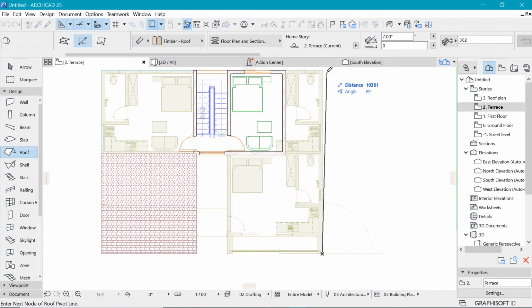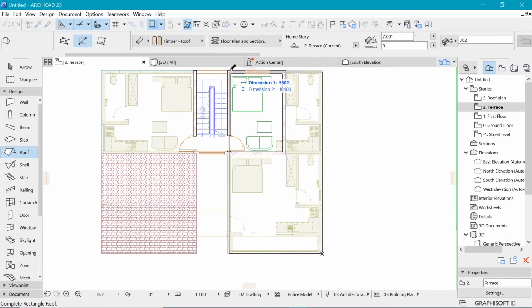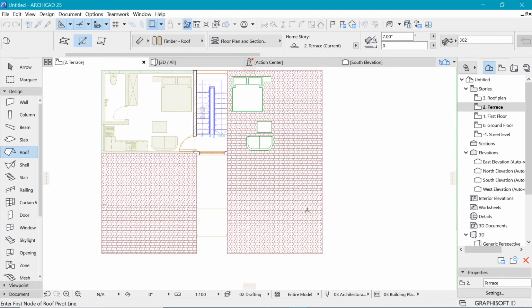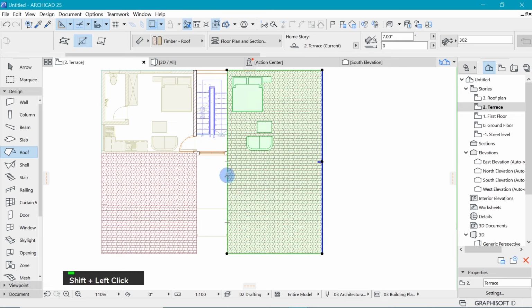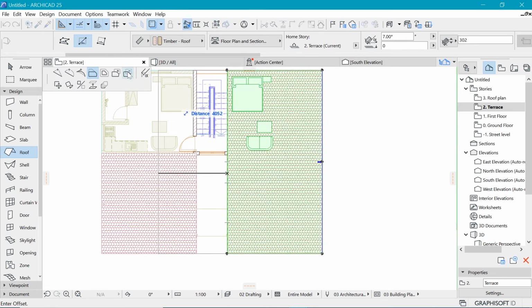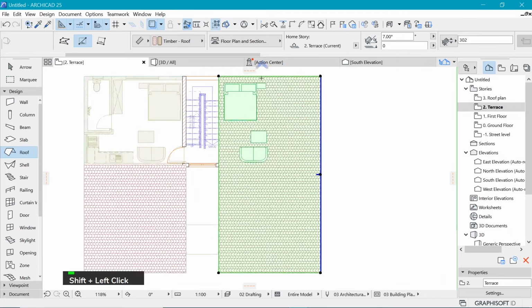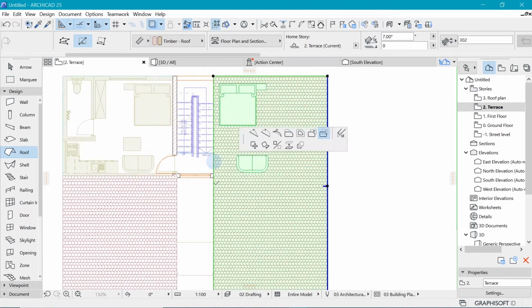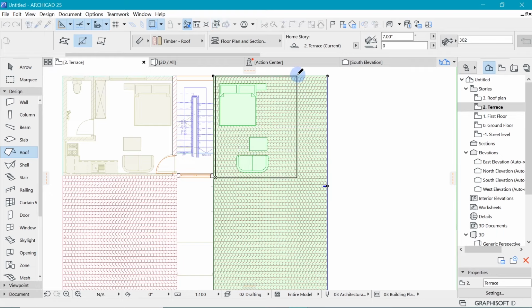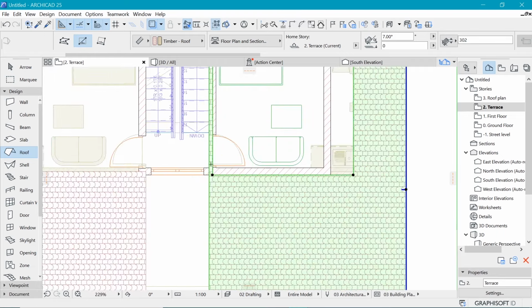We create a line, okay, and then we specify where the roof should face, and then we draw ourselves the shape. But then after drawing this shape, we may want to get rid of this other side, so we say minus by clicking on any of the edges, and then we can go ahead and get rid of this portion. I can't quite see where the rest of the stuff are, so I'm going to sort of assume for now, and then I can go in and clean it up after I have opened up.